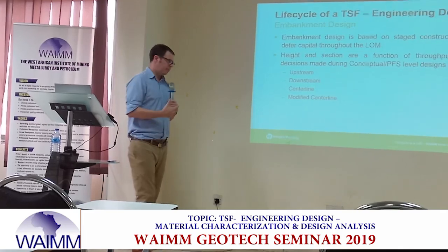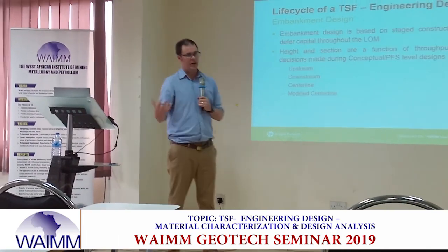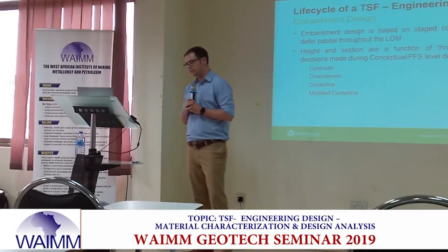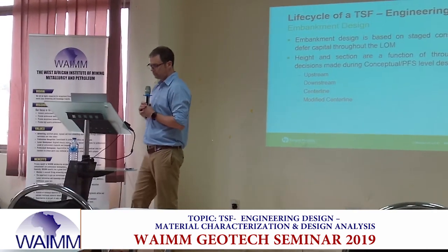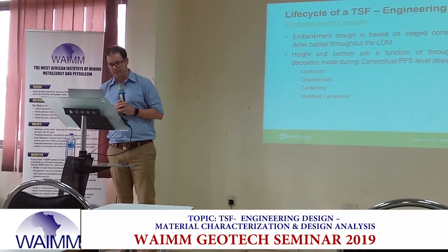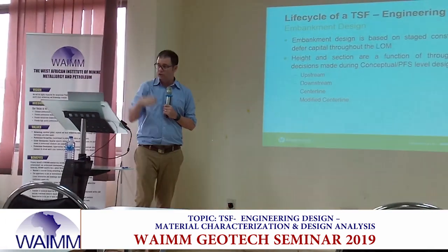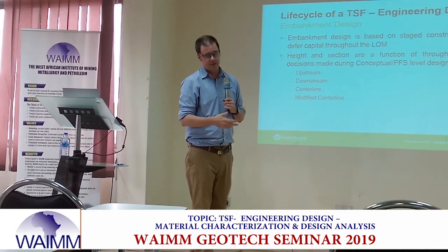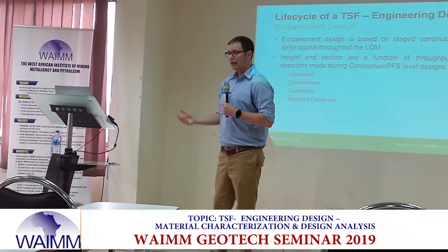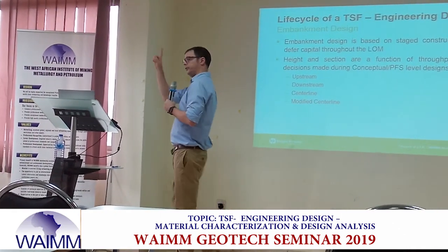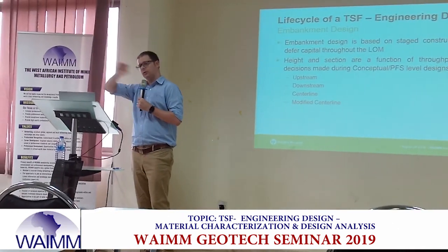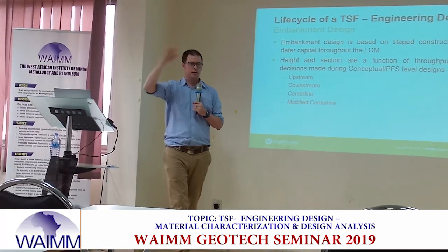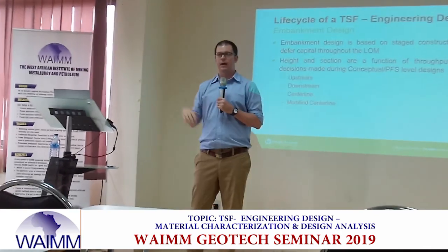Now that we've figured out our basin, we've got a liner, we may or may not have various degrees of drainage. And then we need to talk about our embankment design. Our embankment design should be based on staged construction. The difference between a tailings facility and a water dam is that a water dam is usually built once. And then once it's built, it's operated. Water comes in, water comes out. And nothing ever really changes.